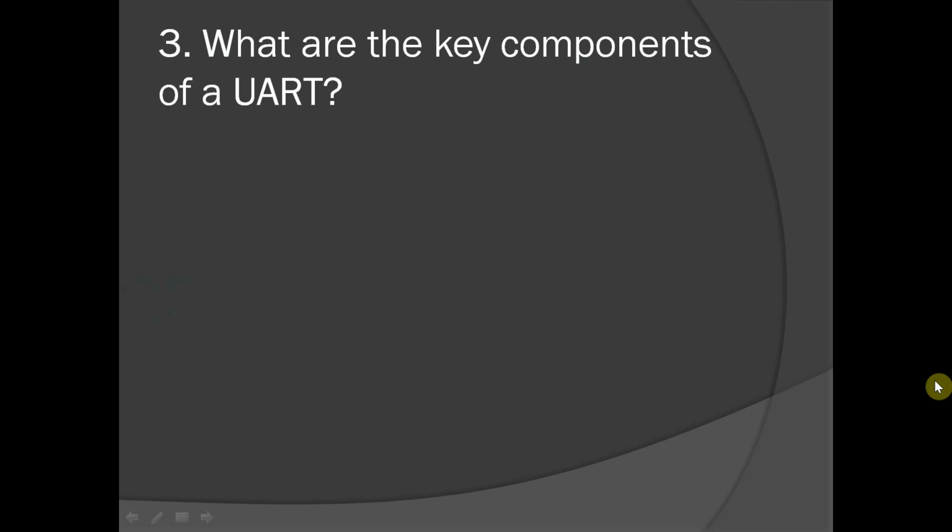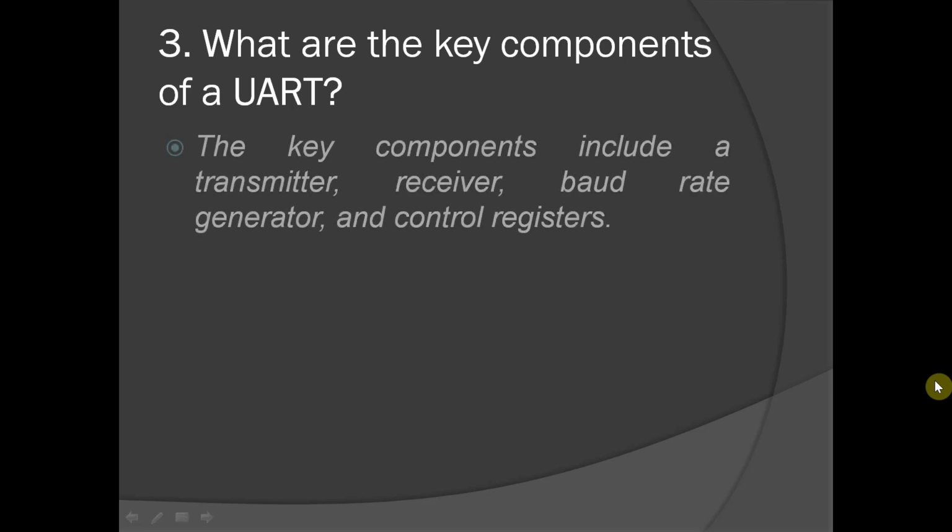Sir, we are using a baud rate, and data bits can be 5, 6, 7 or 8. We also use a parity bit. Before we send the data, we send one start bit, and after the 8 data bits, to show that the transfer is complete, we send one stop bit.